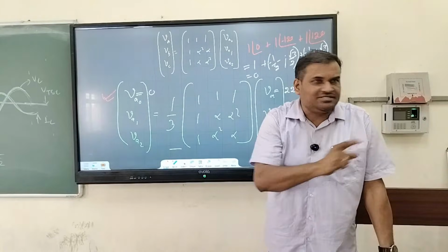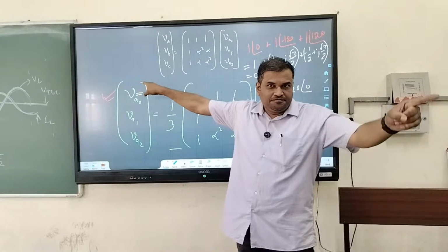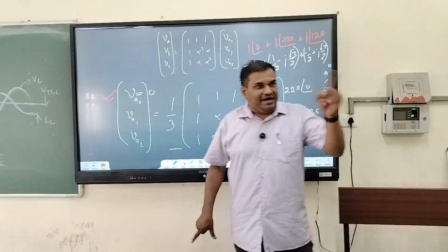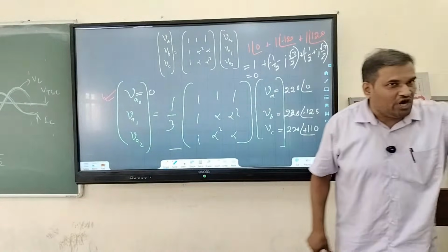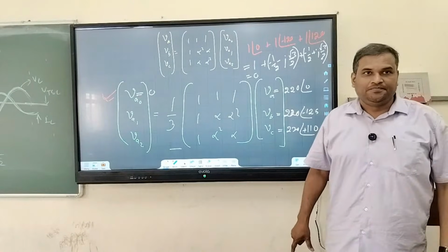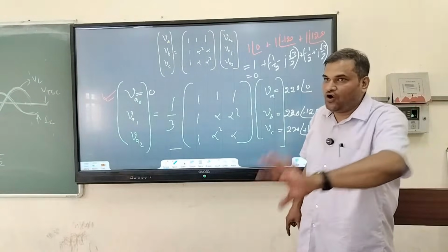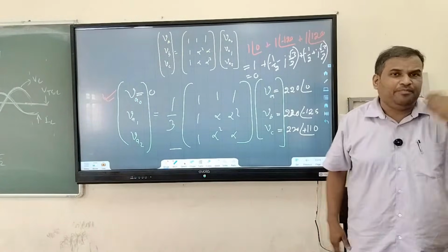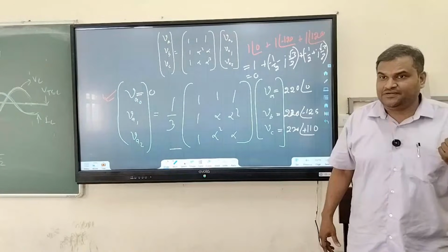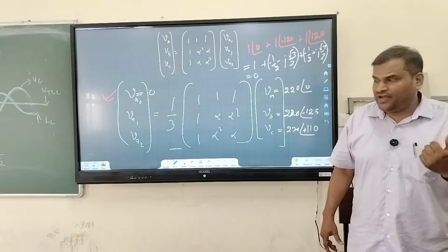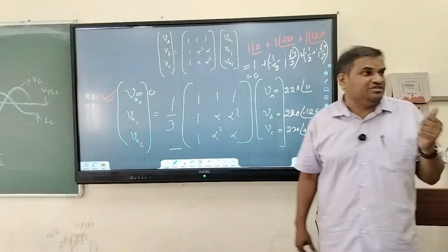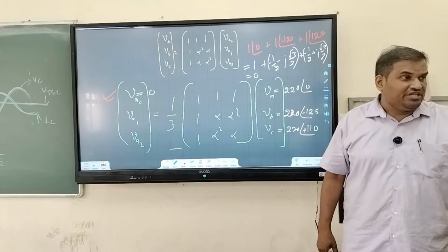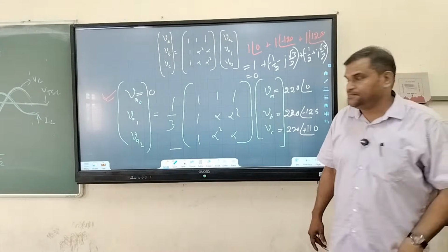If it is not balanced, you will get a zero sequence. You will also get a negative sequence. That is the reason your induction motor is not running at its rated speed. It is running less than that, or there is some turbulence in it. But since we are doing this in the laboratory, we are not able to see that precision. Otherwise, smooth variations can be seen with proper equipment. We can see whether there is flickering or not.